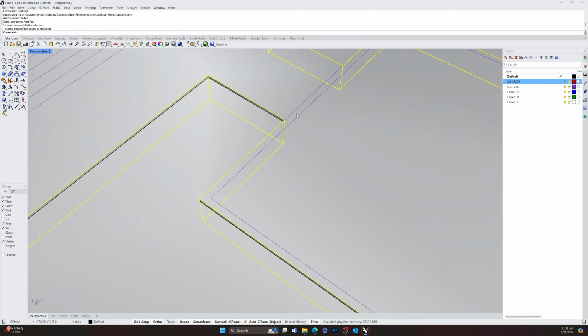And each step I figure is going to be 9 inches. So 9, enter, extrude that up 9. Okay. And then I'm just going to take that, move it from this point to that point there. And I'm going to move it down -9, enter. Okay.